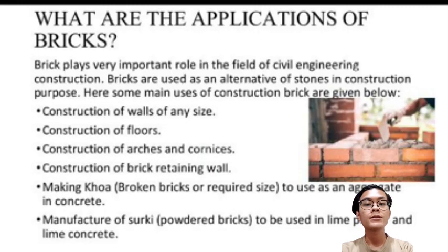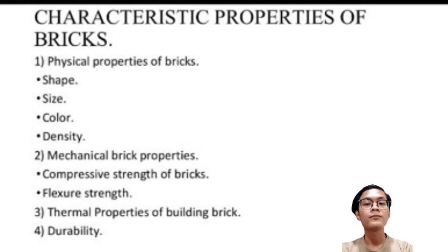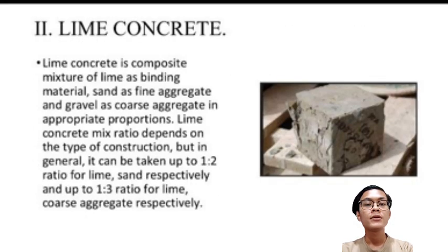This is the application of bricks and the characteristic properties of bricks too. Lime concrete. Lime concrete is a composite mixture of lime as binding material, sand as fine aggregate, and gravel as coarse aggregate in appropriate proportions.